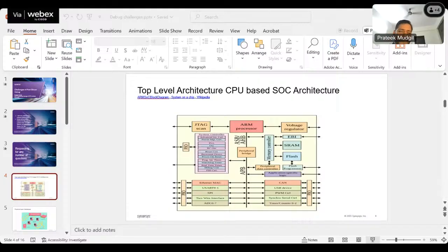Okay, we say that we are meeting the timing to 1 nanosecond, but let us assume that the time period is 0.7 nanoseconds, and we keep 0.3 nanoseconds for tolerance. I'm just putting dummy numbers because it is not allowed to give the exact numbers. So we are going with a timing number of 0.7 nanoseconds, and 0.3 nanoseconds we have kept for the tolerance, for whatever temperature moves or humidity moves or any PVT things that happen in the external world, or to our chip. Then also our timing is met, right?